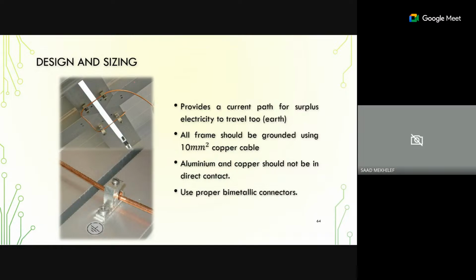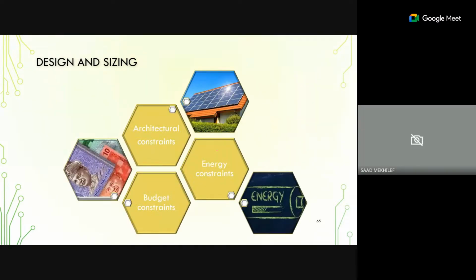If you look into here also for the design, the grounding is very important. You know, the connection, the grounding. You see, we need to have proper grounding of our panels. Okay, especially all the frames should be grounded using 10 mm copper cables. So very, very important. This is for what we call protections.